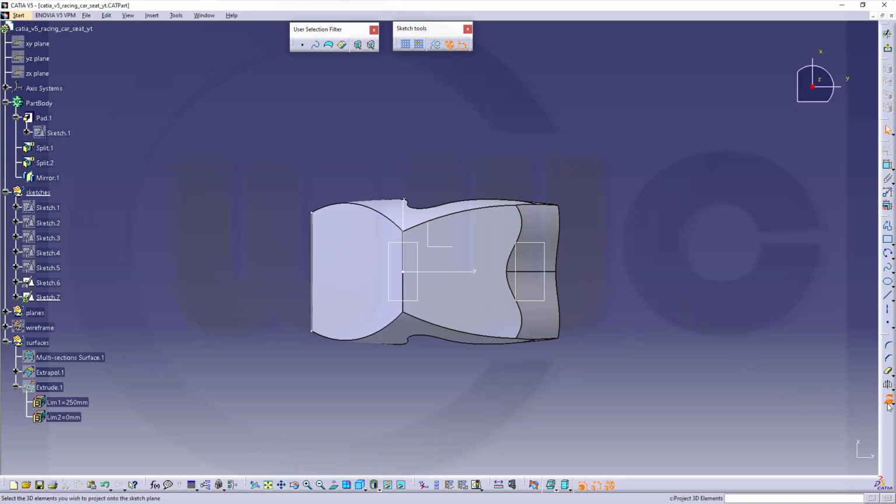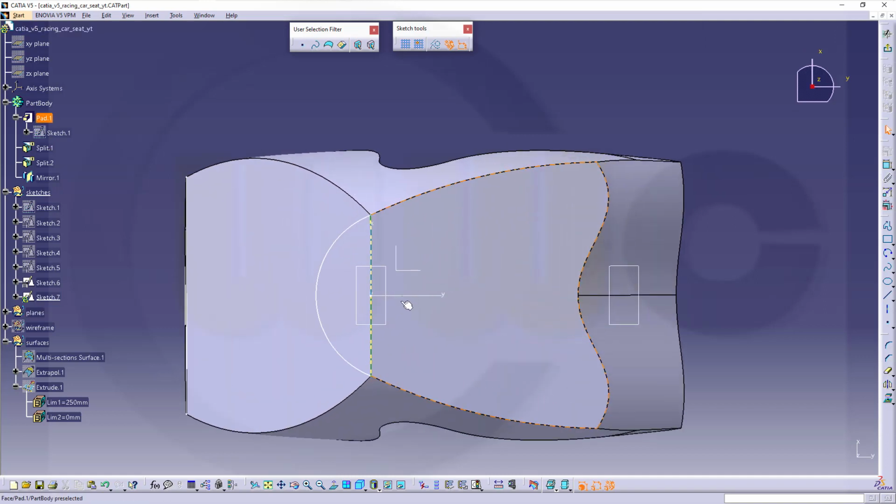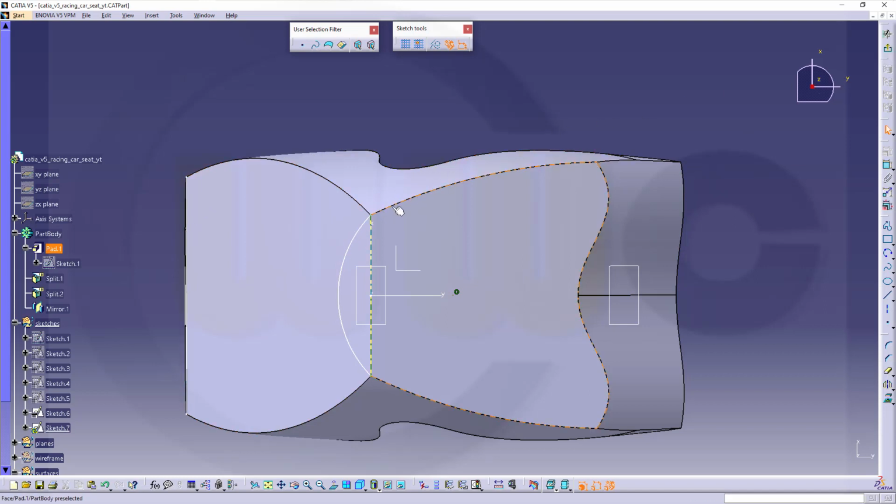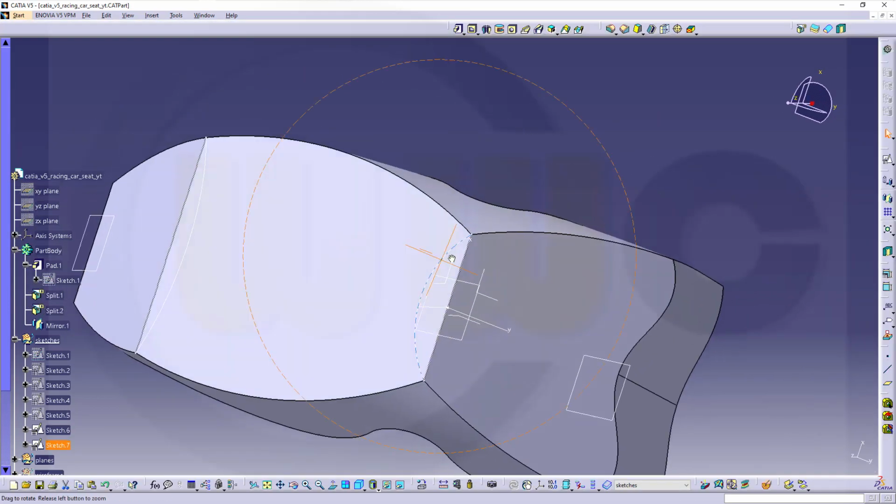And again I need that edge here in my sketch, and now go for an arc from this end point here, don't snap to that one. Where's that center point? There it is, and this one should be, of course, on that axis coincident. Okay, now let's move this a little bit, maybe like that. It's okay. And of course you could go for tangency here. That would be quite nice, but that would make it too big a bulge.